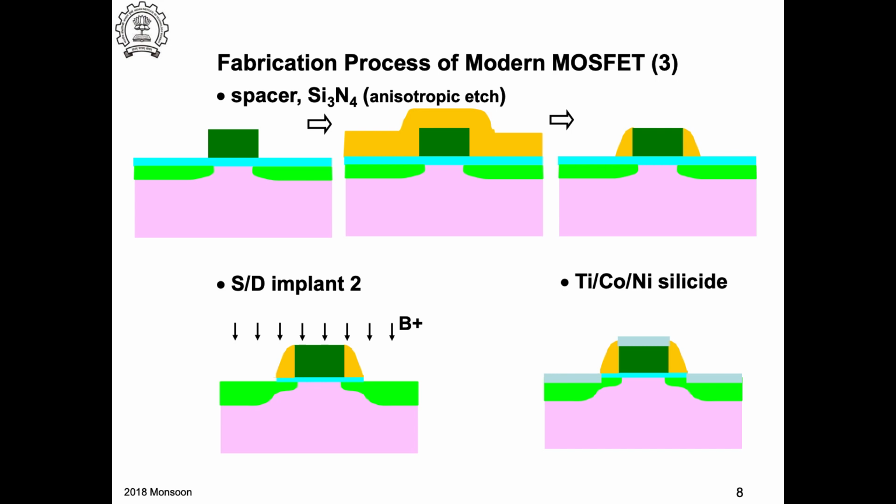Okay, so I can do a very simple analysis. You take this profile, and all the important things are marked on this profile. You're trying to find out what is the concentration of the dopant at this point xm. That is the thickness of the mask. So you know the profile, right? This is your Gaussian profile in the masking material. And you are assuming that the profile shape would not change.